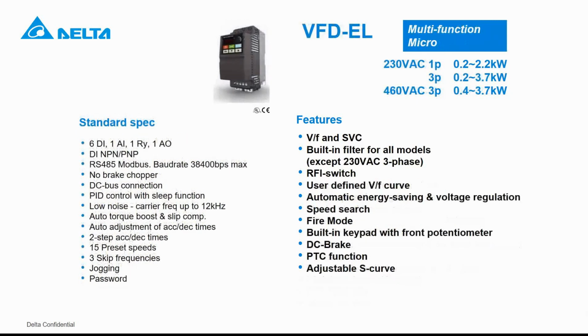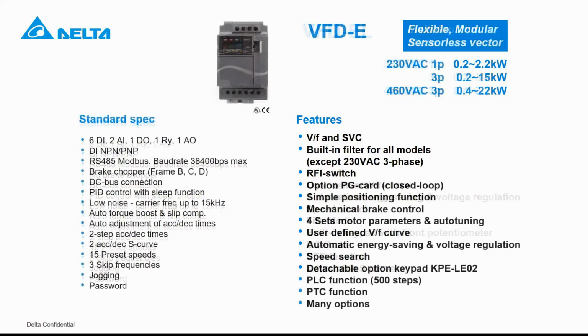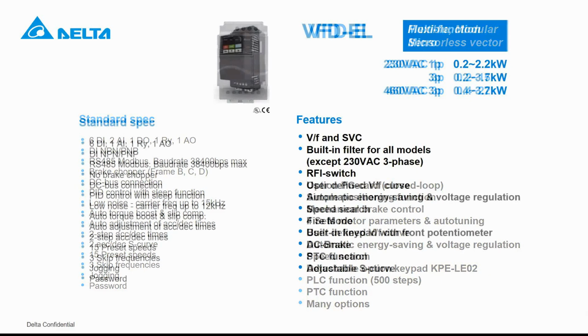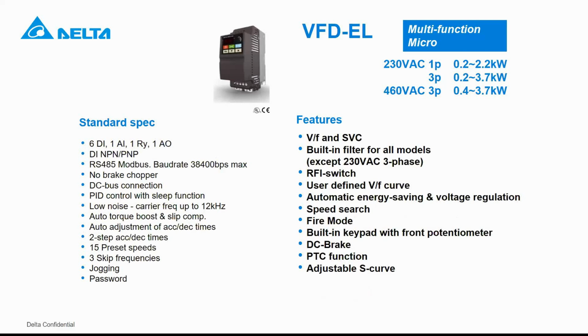And then we also have the equivalent for ME300, the VFDEL, the micro drive. Now, compared to the VFDE, it's good to mention that VFDE does not come with a built-in keypad. So normally the keypad has to be ordered separately. So that will be this one. And VFDEL does come with a non-detachable keypad.